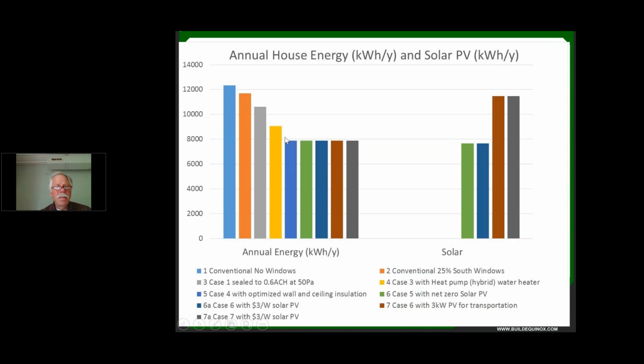the insulation a bit. In the case of 6-inch walls, if we could economically add, at $5 a cubic foot, more insulation in the walls, we'd find that the economic optimum, and we'll see where the economics come in later, would take us from a 6-inch to about a 12 to 13-inch thick wall.